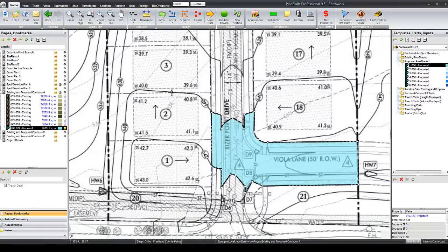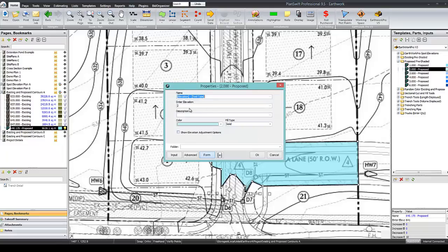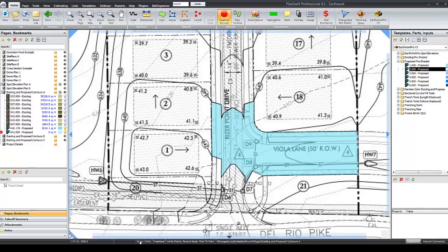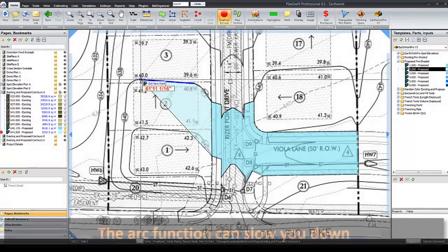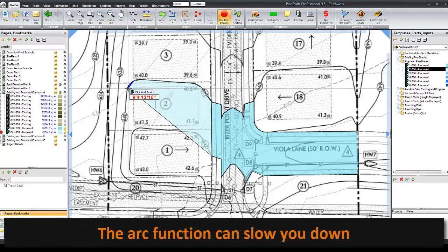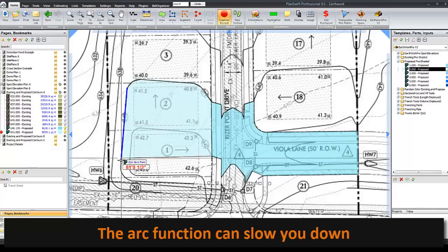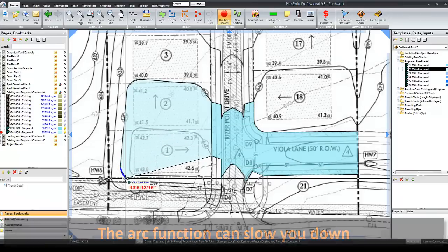Now, because there's still an area for 641 out through here, what I'm going to do is just launch another tool. And again, I'll use a different color of blue. Click the green button, and I'll still type 641. This time I'm not going to adjust the elevation at all, and I'll turn on my snap. And so you can still see I'm still applying this in the area for 641. You don't always have to use the arc if you don't want to.